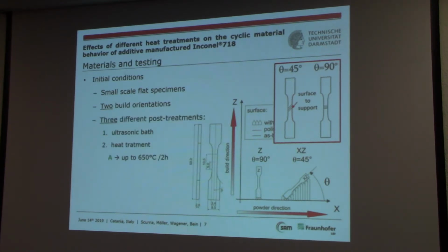We then applied three different post-heat treatments, one up to 650 degrees Celsius, one at 760, and one at 965. At the end we did sandblasting just to clean the specimens.